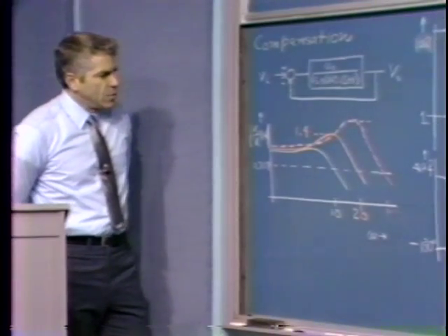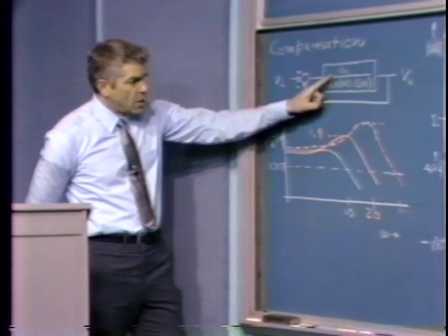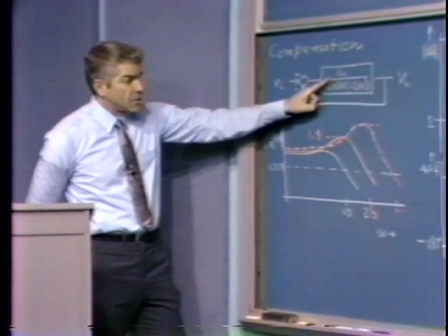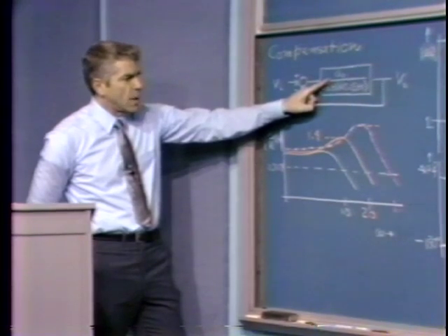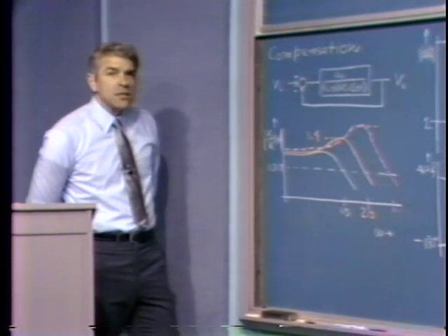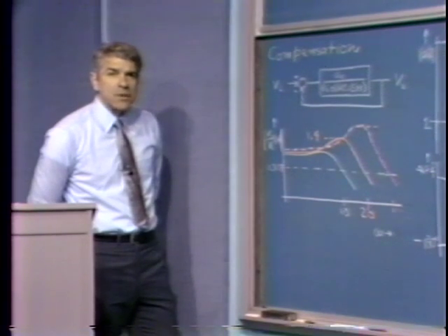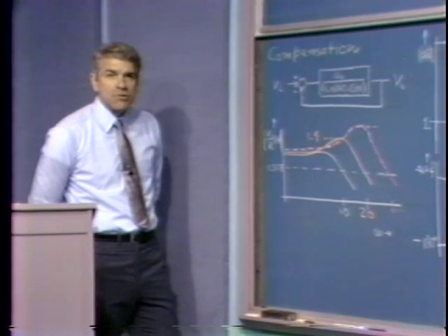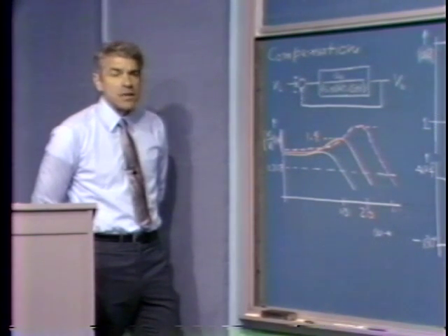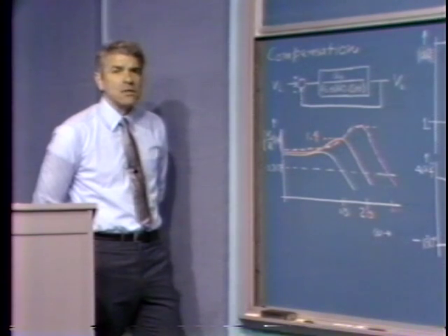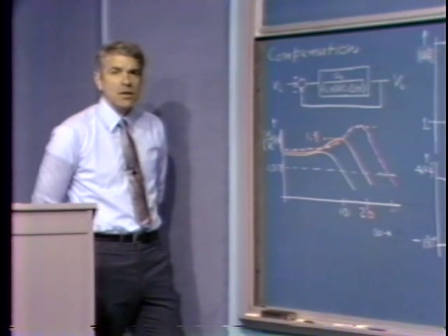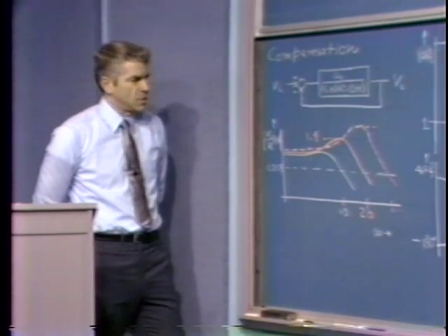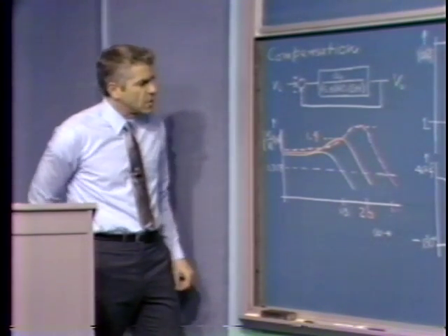As we go to progressively larger values for A naught, the system again becomes progressively less stable. The relative stability of the system drops. And that corresponds very nicely to what we've seen, for example, in a root locus development, where we saw that as we increase A naught in a two-pole system, the damping ratio of the dominant complex conjugate pole pair, the only complex conjugate pole pair for that two-pole system, gets progressively smaller. And so we'd expect this behavior, that the system becomes progressively less stable for larger values of A0 in the two-pole system. And our Nyquist construction confirms that.